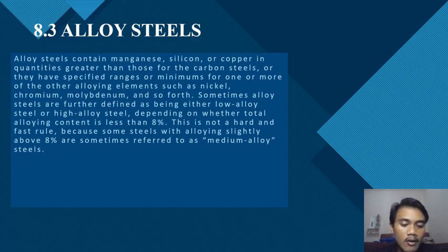Ultra high strength nickel cobalt steel, which we can call Fe9Ni4Co, has good weldability and high fracture toughness. The high nickel content of 9% provides deep hardenability and toughness, and the 4% Co prevents retention of excess austenite in a heat treated part.